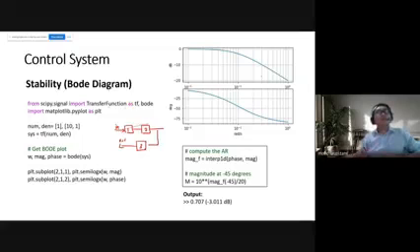So the most important is this. Since I'm still using the transfer function approach, I import the transfer function and rename it as TF so that I can manipulate the TF object. After that I import bode, though I could also use it with an alias, no problem.